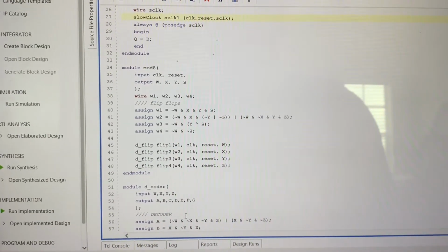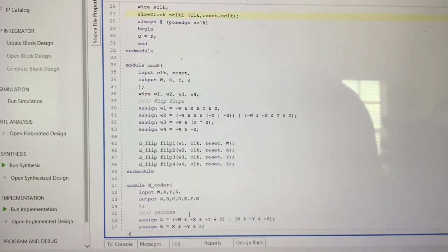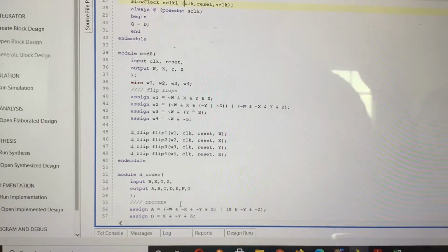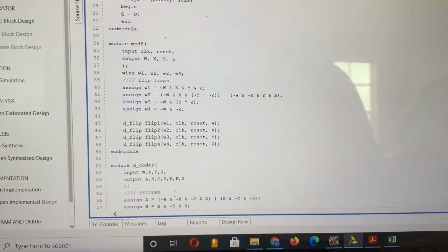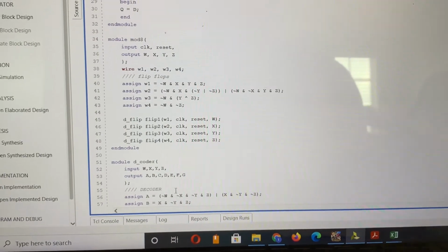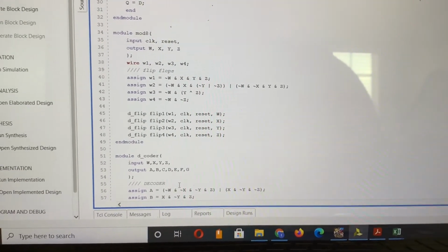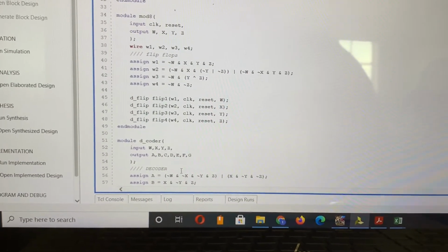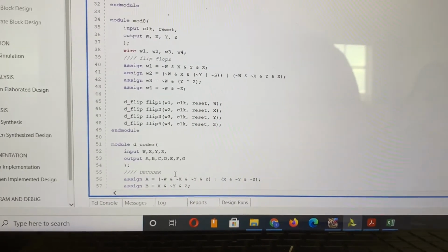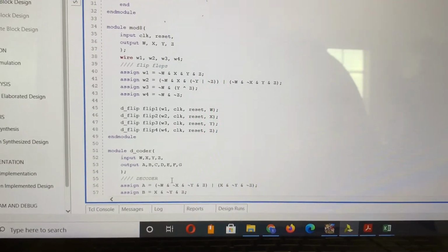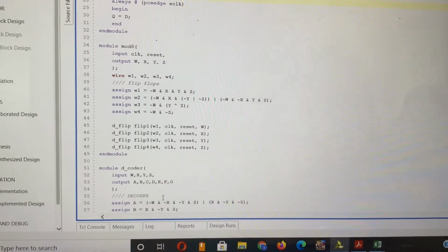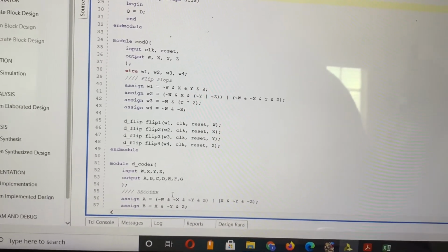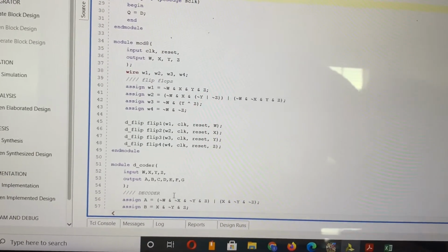My first objective was to determine what I will use to assign the parking spaces to. Each floor has 8 designated parking spots, and there are 2 floors. So I decided to develop a mod 9 counter that's 0 to 8. Spaces 1 to 8 represent the available parking spots, while space 0 represents that there are no available parking spaces. Once the counter makes its way to parking space 8, it signifies that it's time to go to the other floor.